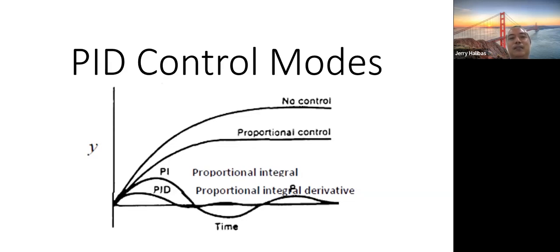So this is the reason that there will be inconsistency, particularly with the different parameters set by auto tune of the PID controllers. So sometimes you have to do manual setting of the PID controllers. Okay, so this is the reason why we have to discuss this one. When that scenario occurs, you have the opportunity to adjust accordingly. Know how to adjust the different controllers, namely proportional, integral, and differential.